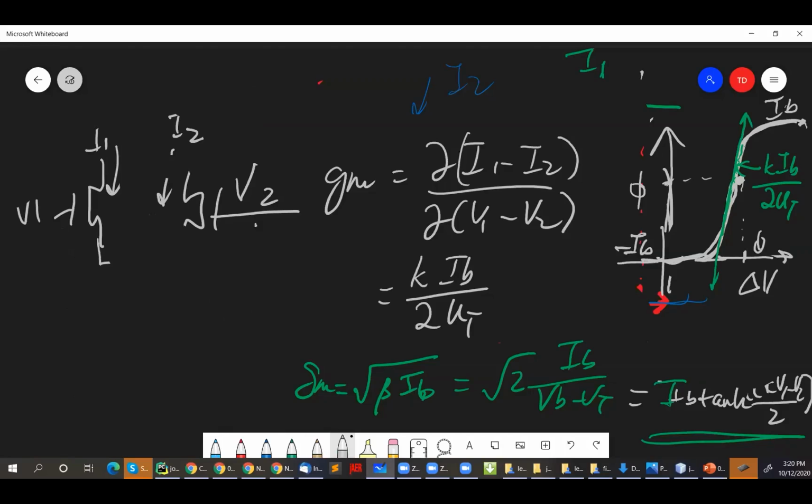So here's my differential pair circuit. And what I want is I1 minus I2, right? Right now, these transistors are dangling. They don't have anything above them. So if I tie this to VDD, I don't get I1 minus I2. I would get I1 and I2 changing, but that's about it. But I want something that gives me I1 minus I2. So how would I do this, you think?